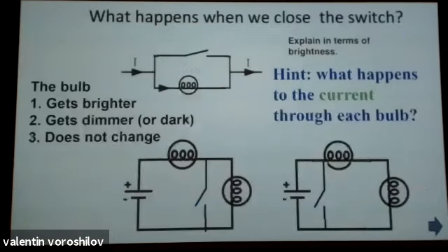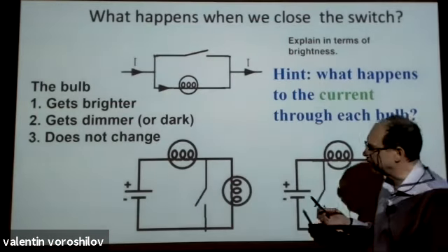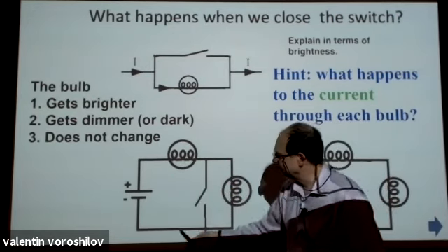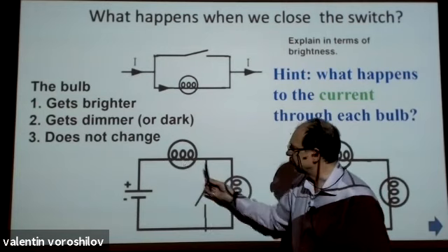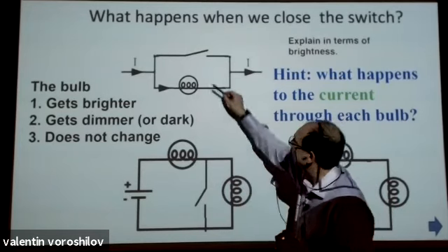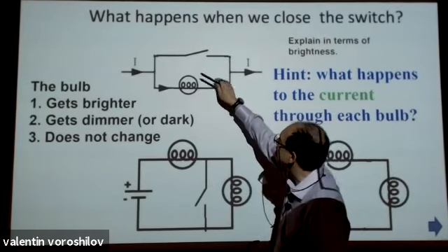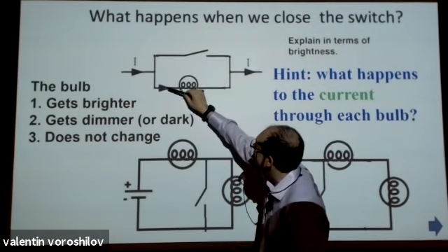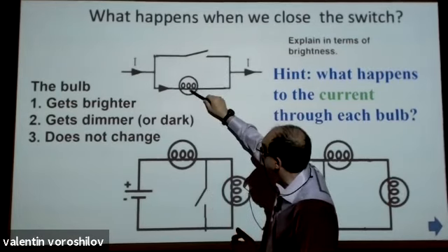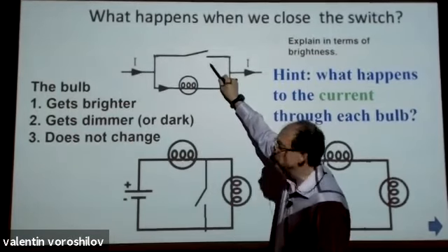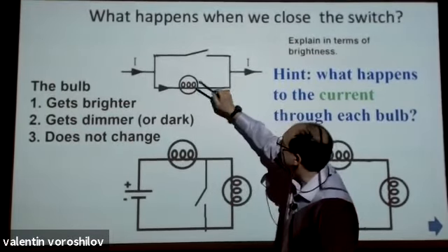So a couple of more similar situations just to analyze briefly. It's not an, well, I could do, but we understand what's going to happen. Now, in this circuit, electric current travels through 2 bulbs. Same bulbs, so equally bright, but dimmer than in this circuit. If I close the switch, well, right now the switch is open, so it's bright, but it's only 1 bulb, 2 bulbs more resistance, dimmer. If I close the switch here, as we did, all electric current goes there, this comes dark.